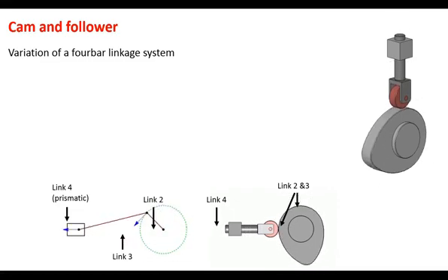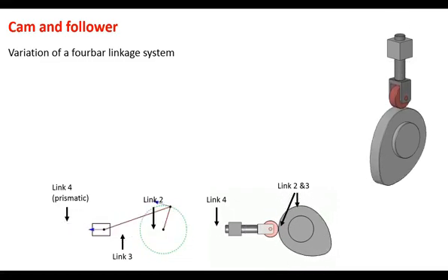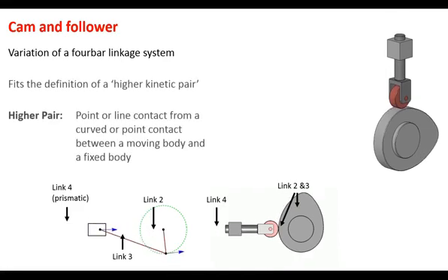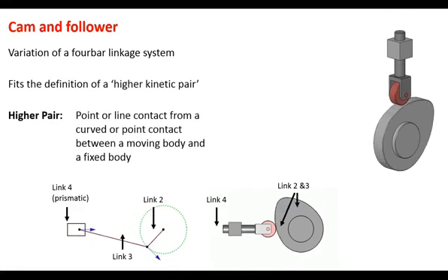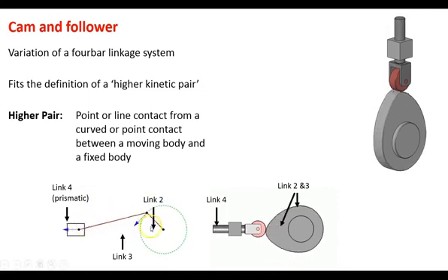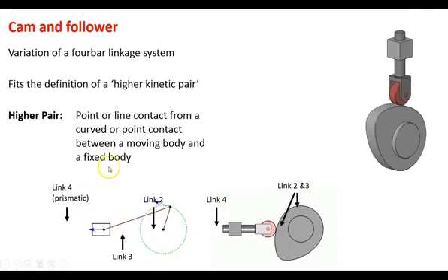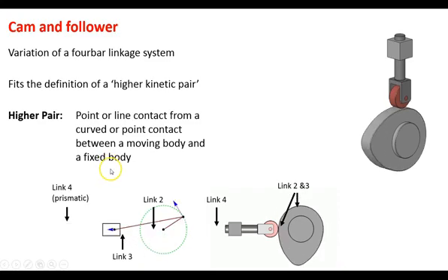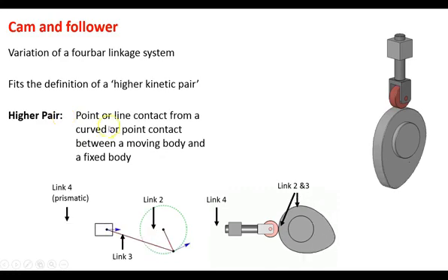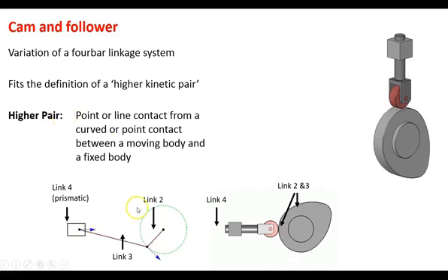And like I said, a cam is a little bit different than a 4-bar linkage in terms of its sophistication, or the nature of its kinematic pair. So if you remember from the first video on linkages, the 6 types of linkages are considered lower kinematic pairs, typically between 1 to 2 degrees of freedom. I think there was one with 3 degrees of freedom.